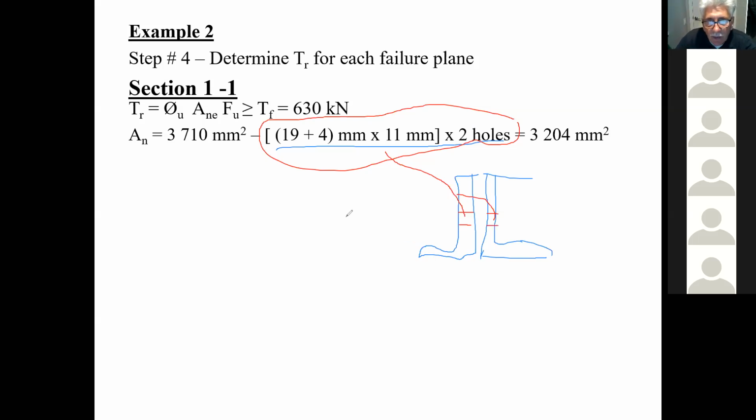Look, what about if I draw it like this? Okay. They're the holes for the bolts. This is the diameter of your bolt. In other words, we use a 3/4 inch bolt, but you cannot make a 3/4 inch hole to put in a 3/4 inch bolt, Emily. Understand? In other words, look. Maybe you'll see it clearer. Okay, so let me see if I can draw it here, as if it's open.